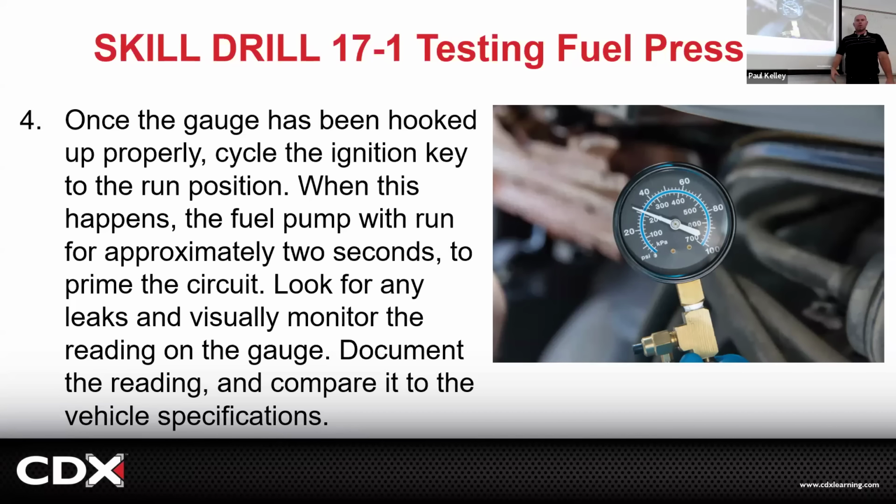Like, I'm good with idle, but at wide open, it's just running out of juice. That fuel pressure gauge will go from a clean 50 to all of a sudden 30 under wide open. That fuel pump can't keep up. That'd be a good diagnosis of a fuel pump. See what I'm saying? So it can vary.